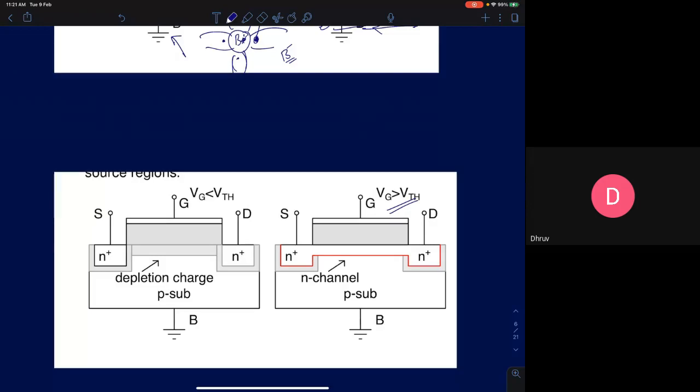If you recall, you must have heard of something called compensated semiconductors. If you start with a p-type semiconductor, with say Na being your doping concentration, and keep on adding donor atoms to this, what happens when your donor atoms become equal to the acceptor atoms?